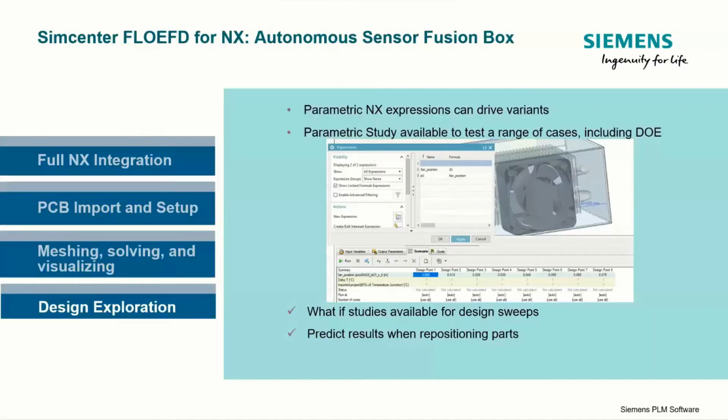All of that was done automated just by specifying to FlowEFD the parametric expressions that NX had already within the CAD model, specifying which ones FlowEFD could drive and what the parameters of interest coming out of the CFD solution were.